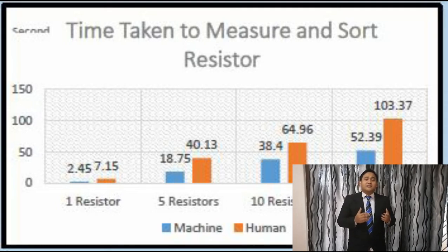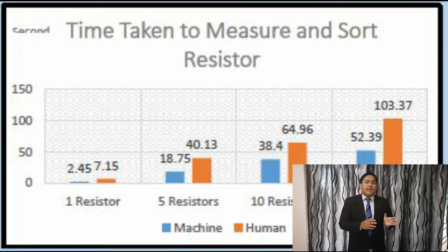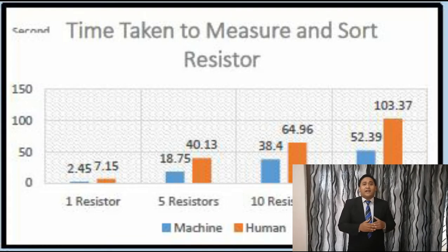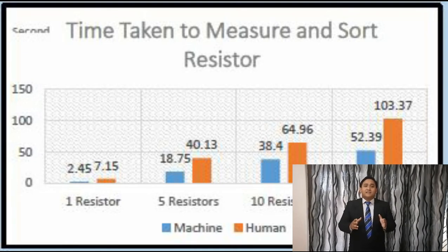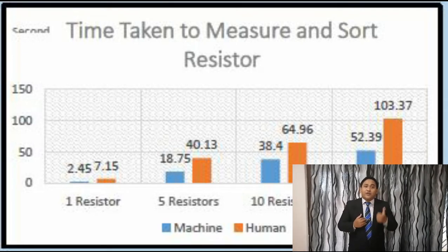Compared to this system, the user does not have to change the range every time. They just need to set the range at the beginning of the system, and then let the machine run and compare by itself to get the result. Based on this analysis, it can show that 500 ohm is the best resistor to use as the known resistor if I want to solve for 100 ohm, 500 ohm and 1 kilo ohm.